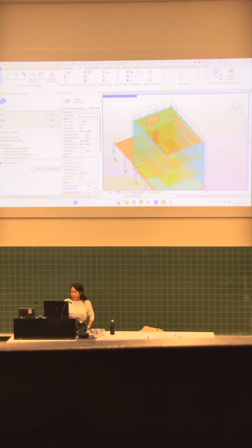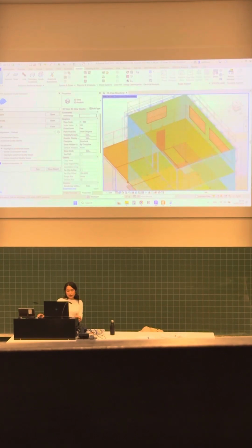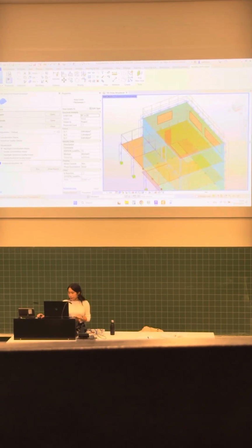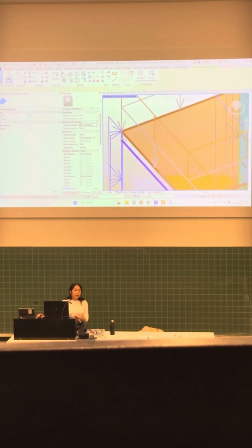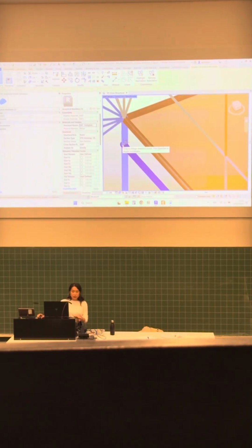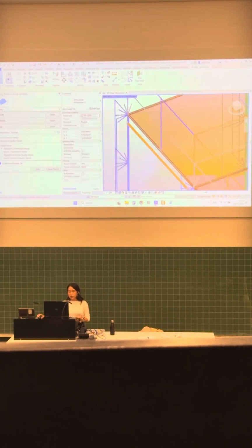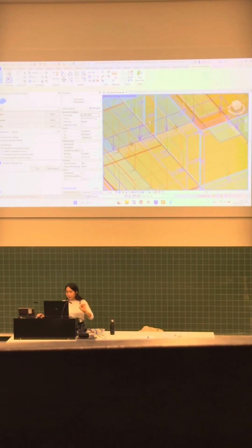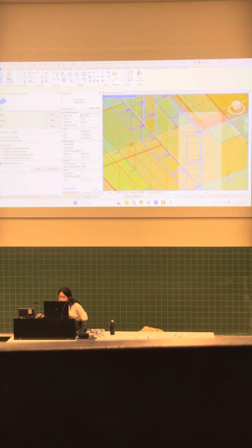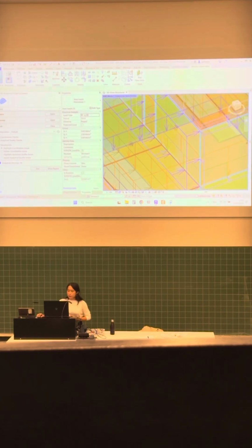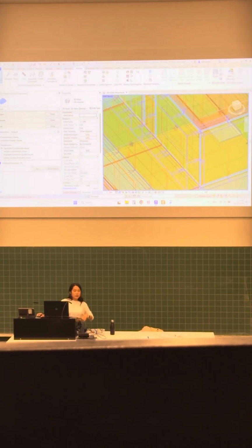I just showed you a small thing before about the adjustments of the analytical model. Again, if it gives a problem in the check, right now you can adjust the analytical model. For example, it will detect a clash, and you go back, you can check and move the nodes, for example. Or the panel, if it's off, you can adjust it. I can't do it right now, but for example, if I hide the element, you can just adjust it manually.